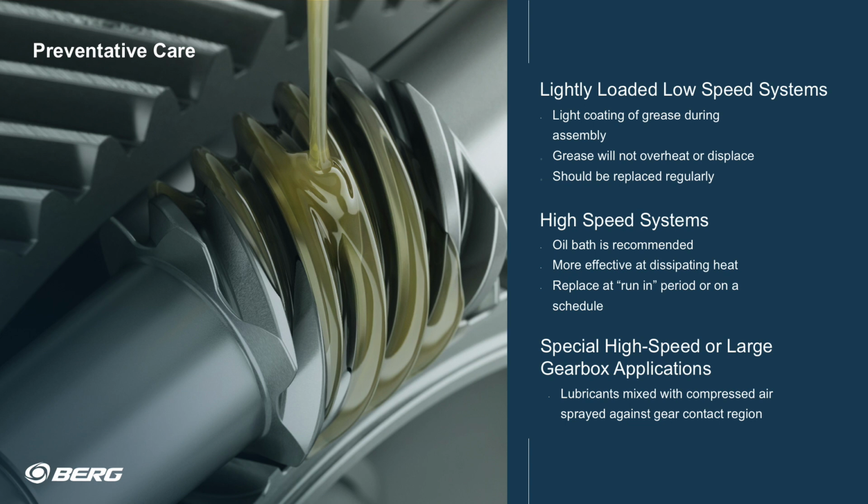For lightly loaded, low-speed systems, a light coating of grease during assembly may prove to be enough. Because the system is moving slowly, the grease is not likely to be flung off the teeth. Additionally, because it is lightly loaded, degradation of the grease may take a longer period of time. Care will need to be taken to ensure that the thermal capacity of the system, including the lubricant, is not exceeded.